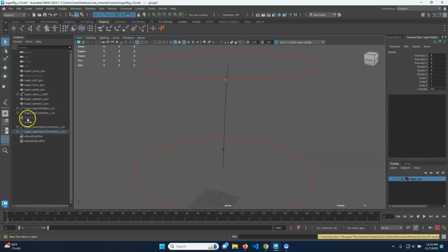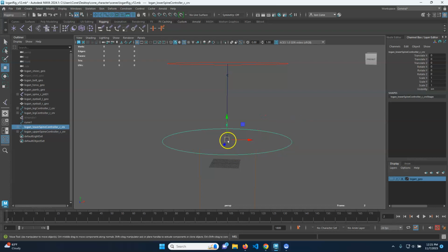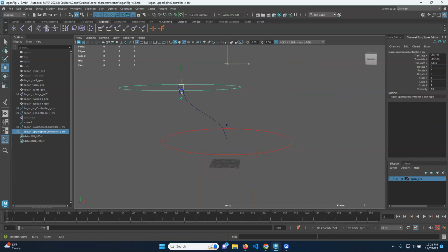You might find it easier to actually grab them down here. Also be aware it's going to put it inside of a group. You might see a message about putting it in a group. Just know that that's why that's happening. It's because it works based off of relative position, and in order to maintain its current position, it has to create a group so that it doesn't fling out. Okay. So now what you'll see is that when I grab the bottom here, it'll move the curve like this. And when I grab the top here, it will move the curve like that.